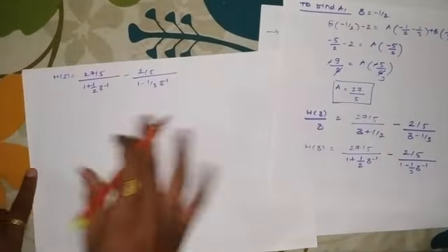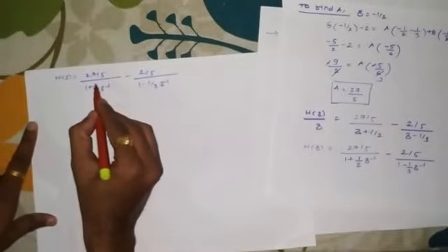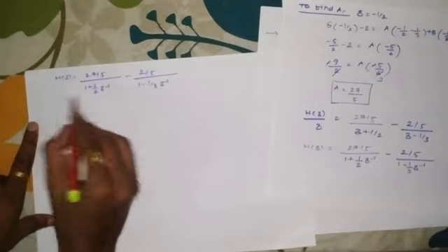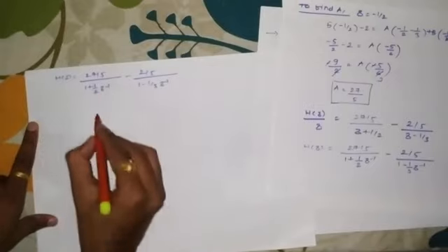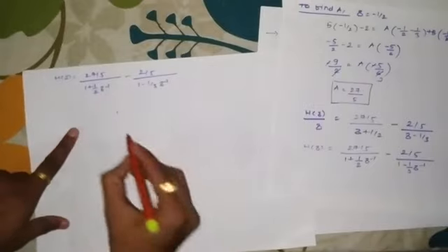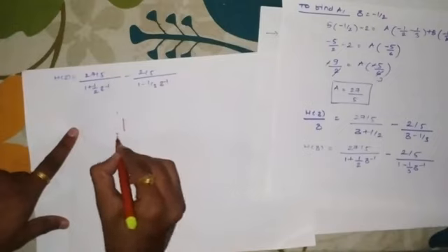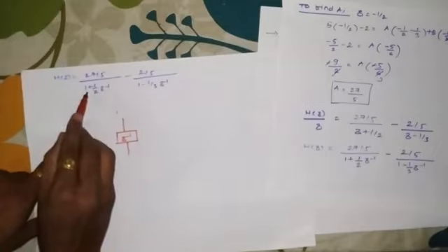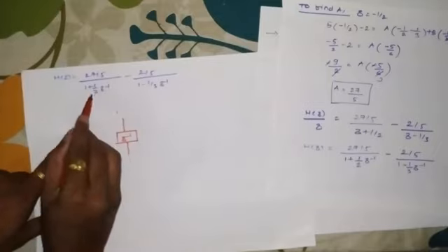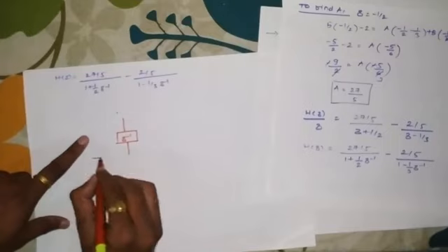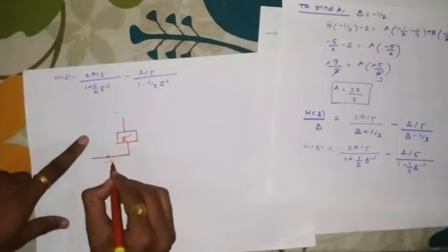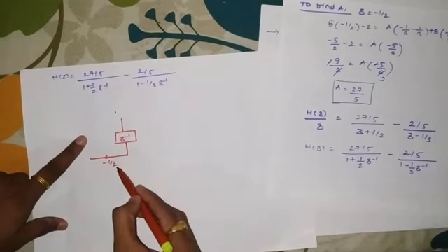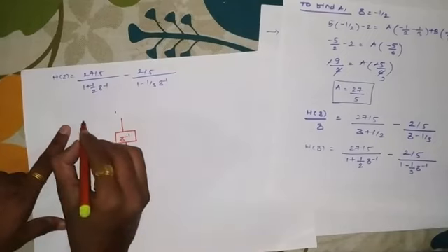So first we'll come across this one. This is our H1(z) and this is H2(z). These two systems are added with each other. Now for this case, you can see only one delay element is required. That means we'll take the first delay element as z inverse, and only one adder is required. Now for the z inverse, here it is plus 1 by 2. Now by our method, we have seen this, it should be minus 1 by 2. So remember, whenever pole coefficients are positive, in realization they become negative, and it should be added.